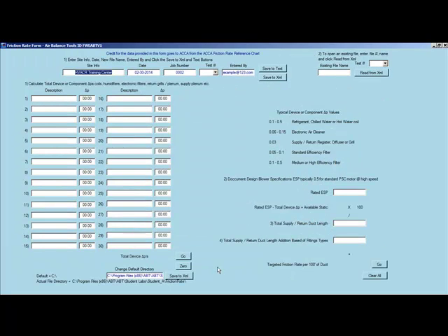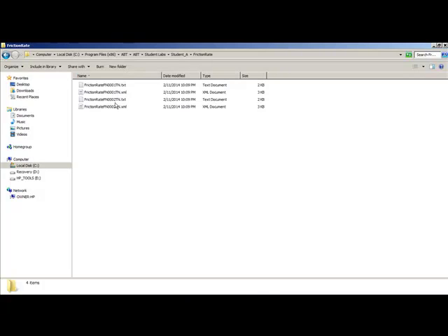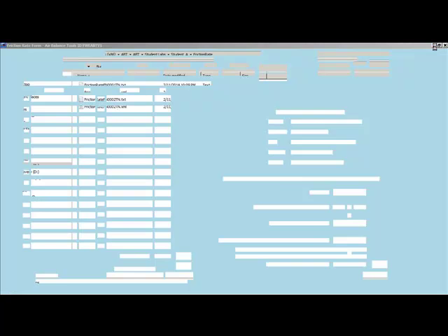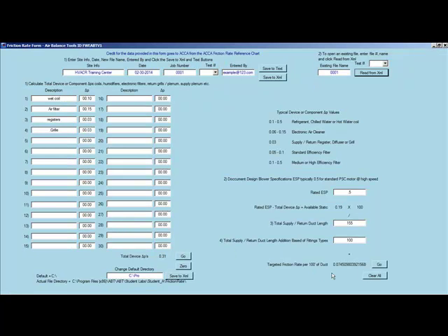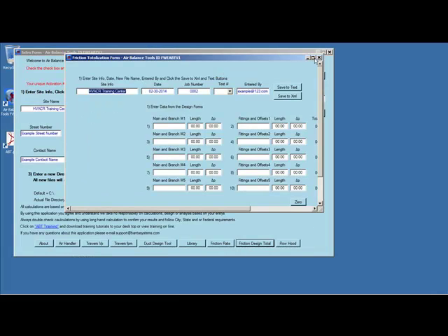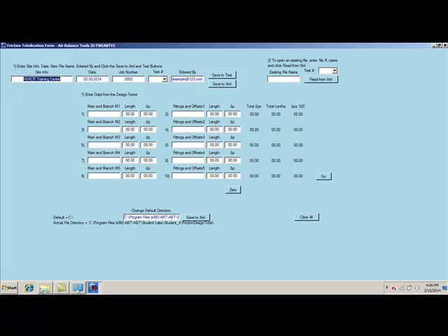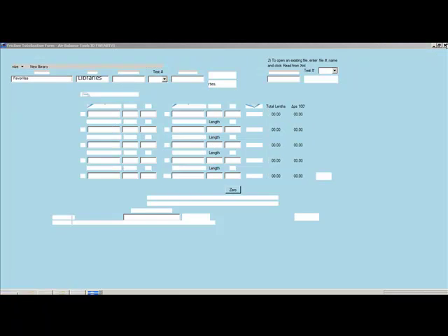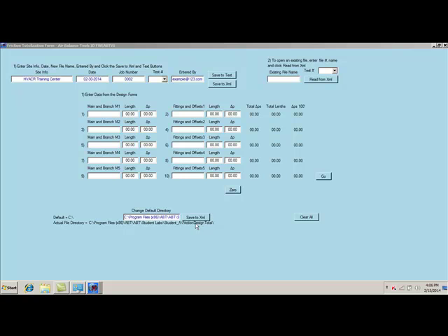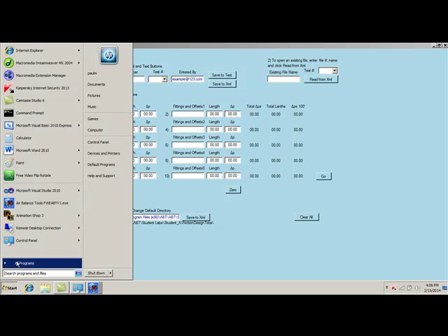Our friction rate form, same thing, auto population from the entry form, auto population for the directory from the entry form as well. In this case, we're using a friction rate. We have file numbers 1 and 2. And so this is the targeted friction rate per 100 feet based on the friction rate reference chart calculation. So we have the friction design totalization. In this case it was friction design total where we were using this.